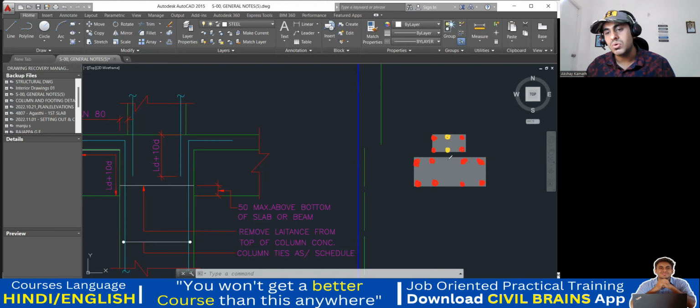Now what you'll do, because you don't have any rebar here. That's the first thing. Second thing, this rebar is already taken here, so there is no point in cranking and taking it here. And this much crank also you cannot give, because this slope is more than 1:6. In that case, this 2 rebar will anchor it. We'll bring up, let us say, this red color is your 16 diameter. This yellow color is a 12 diameter.